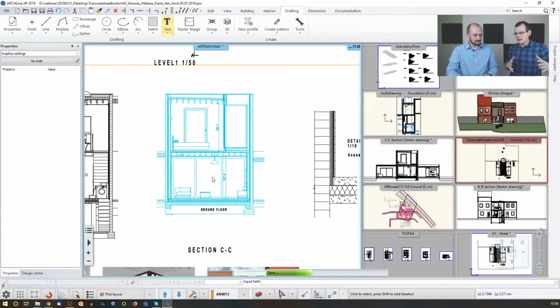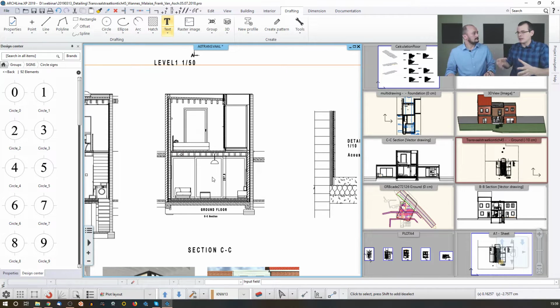When you imagine that you have the same kind of designs coming up over and over again. Let's assume that you have 5 different types of plans that you do. Then you don't have to do the documentation for each and every project that comes up. Instead, you could create templates for yourself. The template means the building model and the plot layouts with the sections and elevations. So you can open up the project, make the necessary changes demanded by the certain project, maybe move the partition walls and things like that, and then you can just refresh the plot layouts and refresh all the views and elevations.